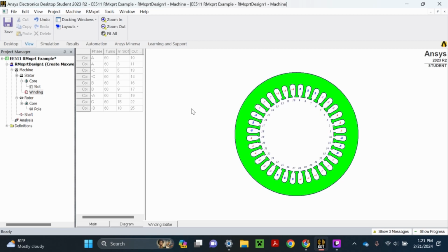Plus, when you have high frequency currents, they tend to go to the surface of the wire. So when you have solid, you have less efficient space because they don't stay at the center. They go, but in the other case, you have more cross section. So all of them, I think the software will find that for you. I don't think that's something you should be worried about.